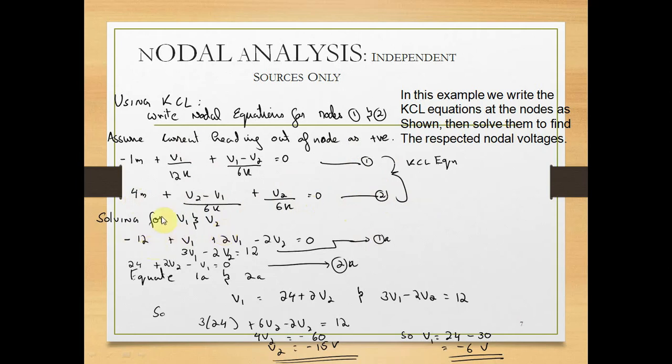First we take this equation, keeping the numerator the same. Hence here we multiply by 12. There is 12 milliampere and a kilo ohm, both are cancelled. Hence it is minus 12 plus V1 plus 2V1 minus 2V2 upon 12k, and 12k multiplied by 0 gives 0.